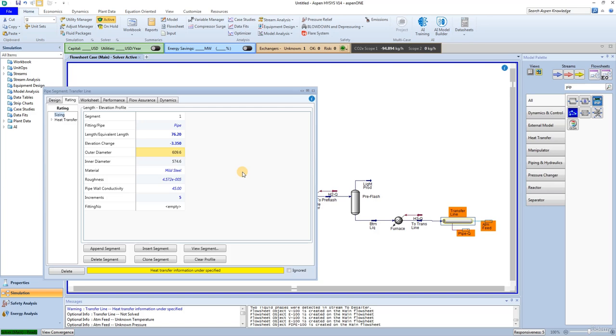The heated crude transfer line continues on into a standard 90 degrees elbow and then into a further run of pipe to meet up with the atmospheric column. You can add these piping items here in the rating sizing form by simply appending additional segments. The pipe segment also allows you to clone existing segments, making it easier to build and define similar piping objects.